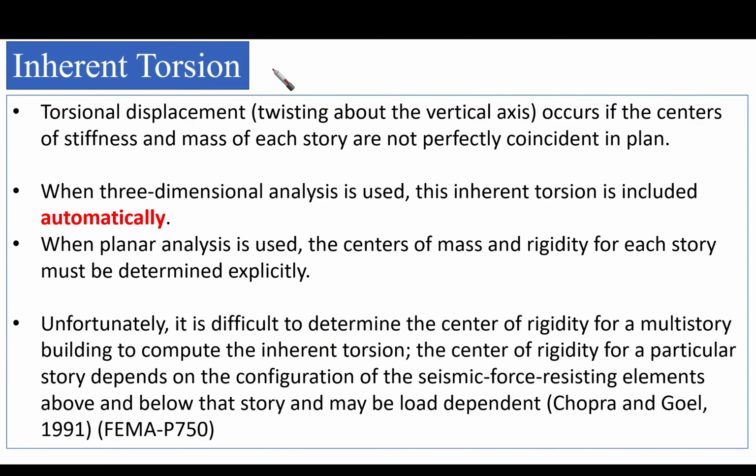Okay, let's talk about the inherent torsion in the beginning, and actually it's an introduction for the inherent torsion. As we know, torsional displacement means that the twisting about the vertical axis occurs if the centers of mass and stiffness of each story are not perfectly coincident in plan.